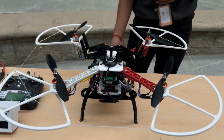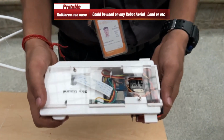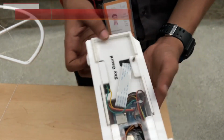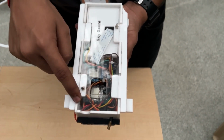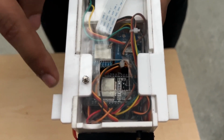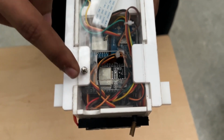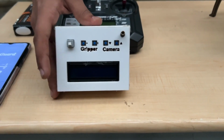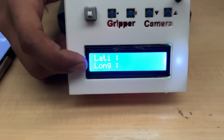Now let's talk about the attachment. The attachment module is fully detachable. As you can see, there are 4 main components in this. When the person is detected by the Raspberry Pi, it sends signals to the ESP32. The ESP32 takes the current GPS location and then sends that GPS location through LoRa to the receiver. The receiver will receive it, and it will display it on the LCD screen. As you can see, longitude and latitude.